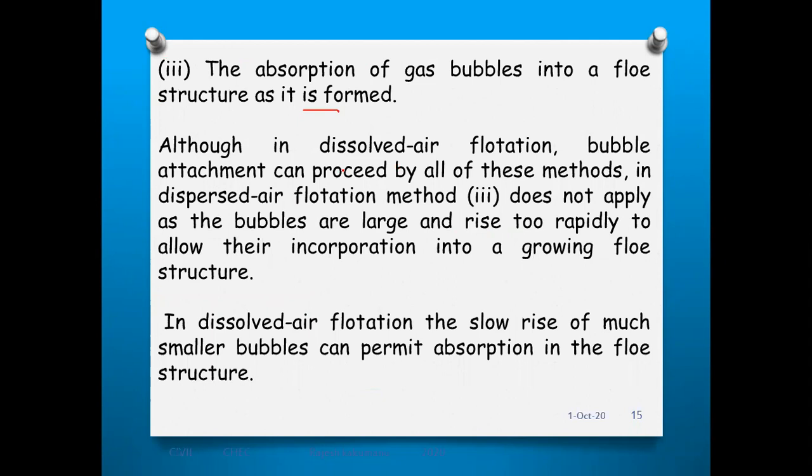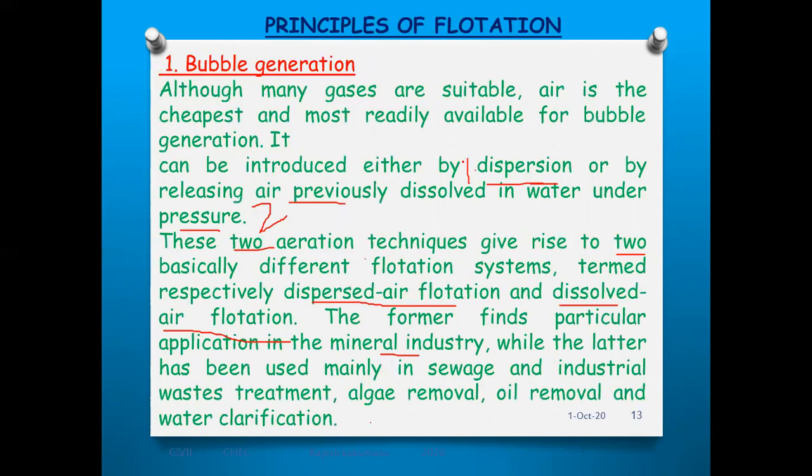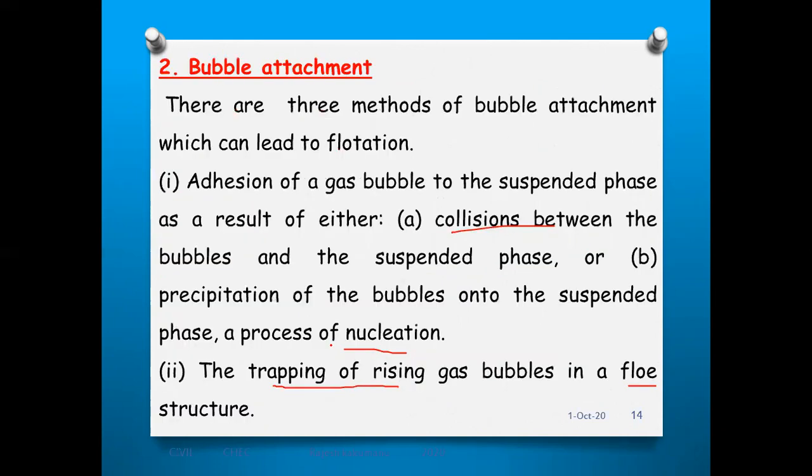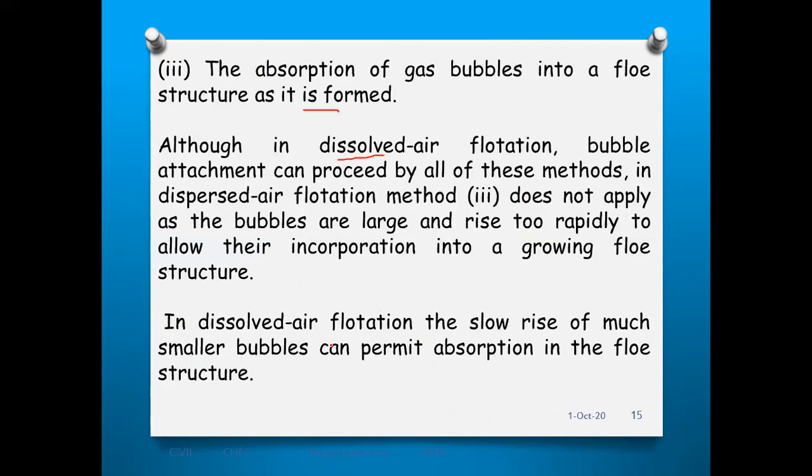Next, in dissolved air flotation, we are discussing only dissolved, not dispersed. Why? Because dispersed air is mainly used for mineral industries, whereas dissolved air is mainly used for water treatment. So in dissolved air flotation, bubble attachment can proceed by all these methods.